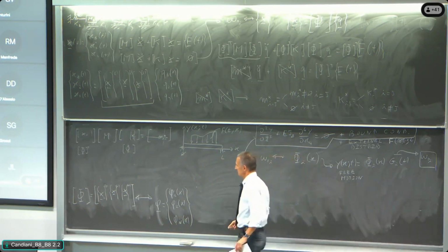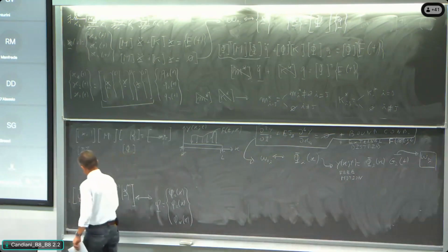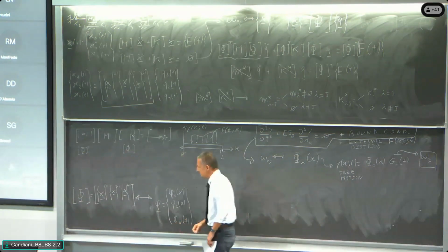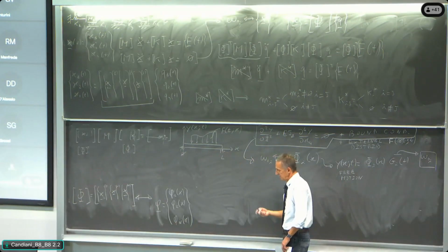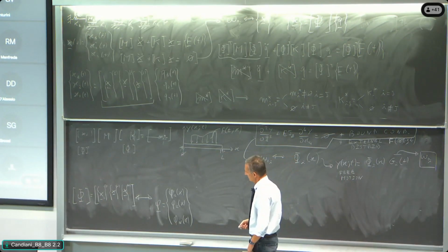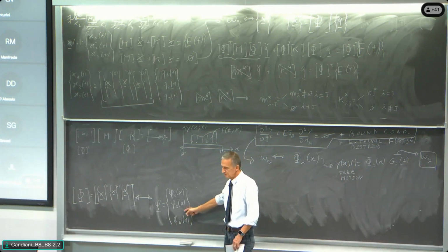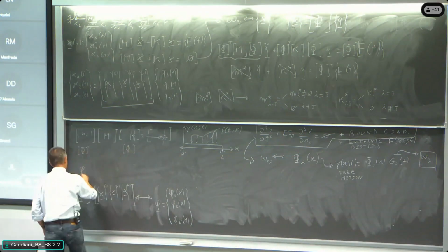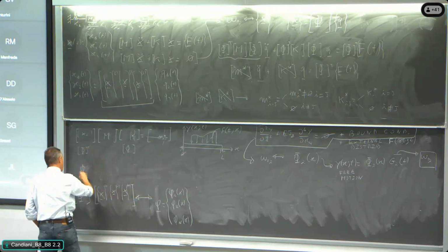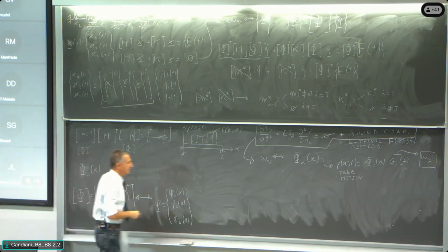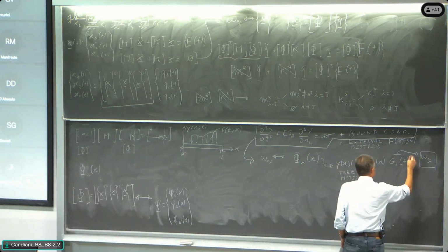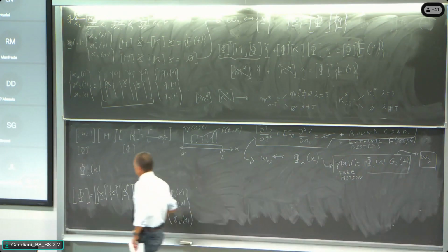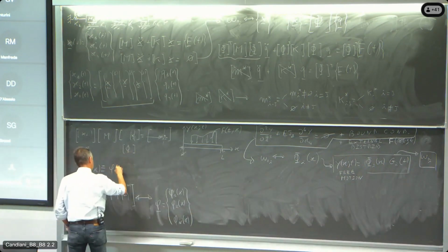Now keep in mind that the transformation matrix, which is the fundamental tool in the n degree of freedom system, becomes the vector of the eigenfunctions. In the notation of the slides, the function was written as phi i of x. For some reason, when I wrote those things, I used a different notation, but it is coincident with phi i of x.